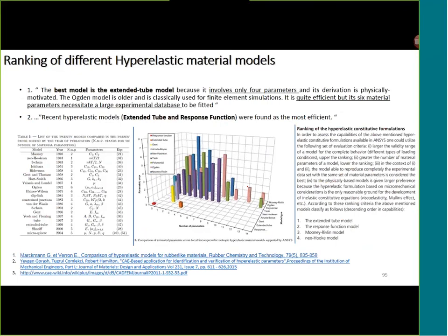And we have seen many hyperelastic material models. As I mentioned, for certain stress strain curves, more than one material model can result in the same response. There are certain stress strain curves which cannot be captured using all material models. There may be one or two material models which will capture your response well. So it is important to do trials with various material models and identify which material model is really suitable for you. And also all these material models have been developed over years, starting from 1940.